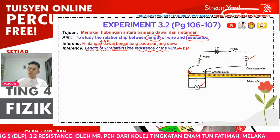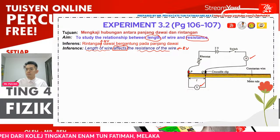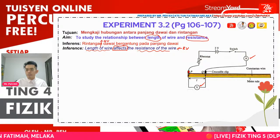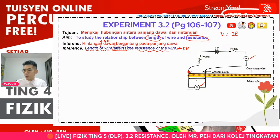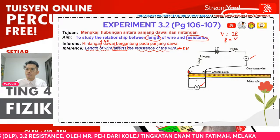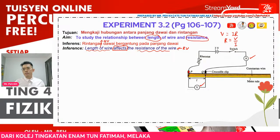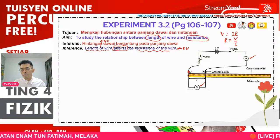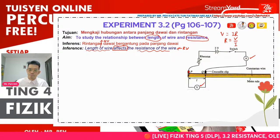We measure the current by using the ammeter, and the voltage by using the voltmeter, and you can get the voltmeter reading. Again, we use V equal to IR. Here we are using a constant wire, right? So we use this formula: R equals V over I. After you get the readings V and I, you have to calculate R so that you can get the reading of resistance.